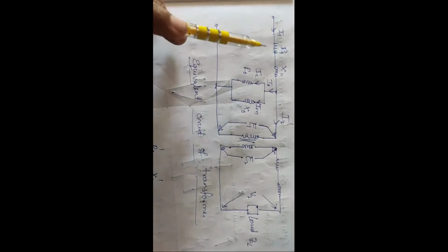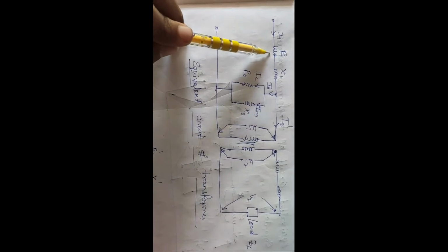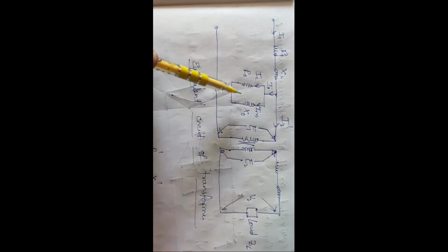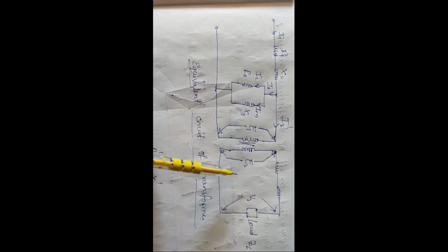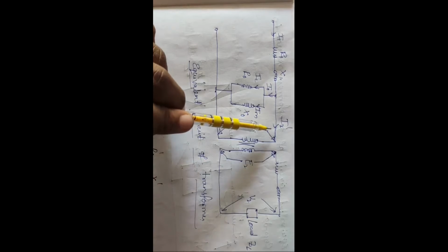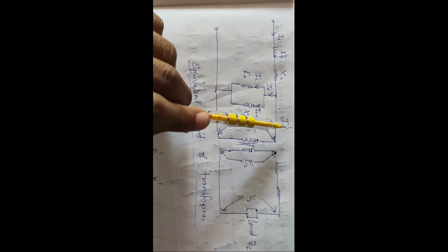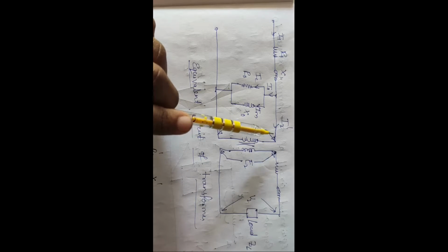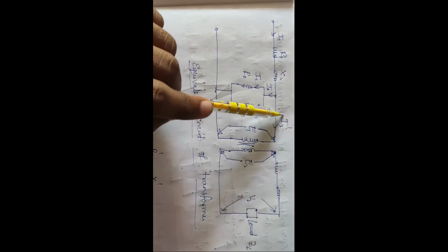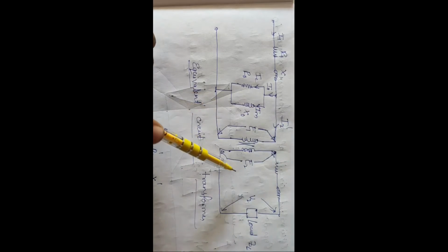So see, on the primary side we have R1 resistance, X1 reactance, and this is a no load component we already discussed. And we have I2 dash. I2 dash we have already studied in the under load conditions: some secondary flux will be produced. To compensate that one, we have to add this I2 current.